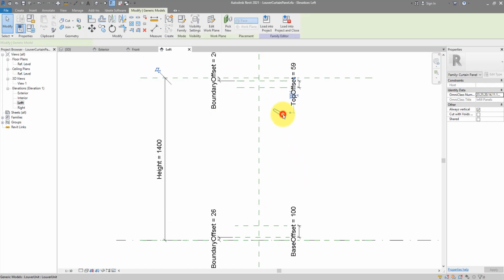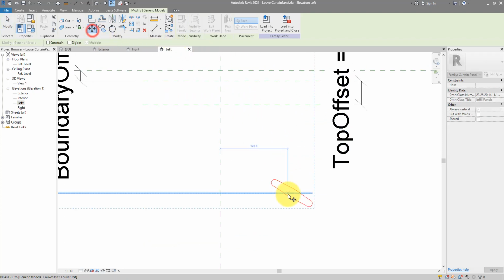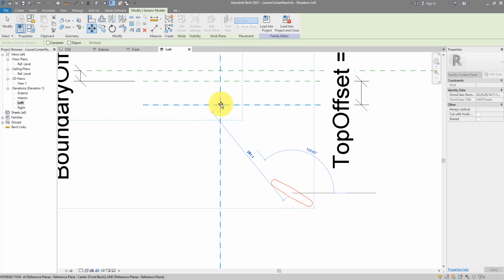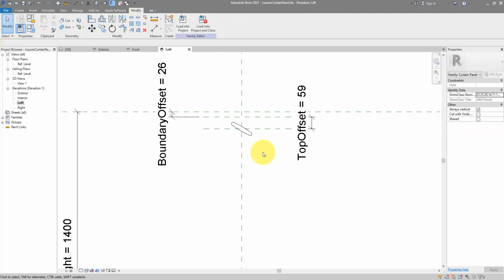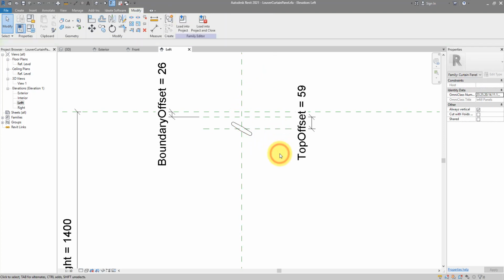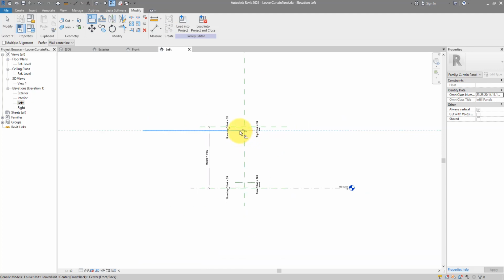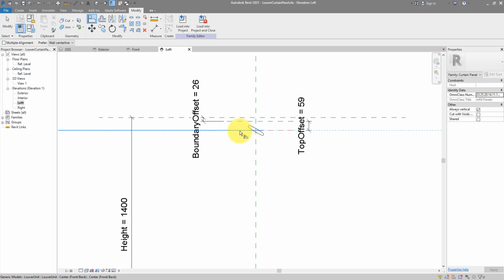Alright, looks like we're ready now to move our louver unit to where it should be. Let's go to the move tool and bring it right there. Now, to make sure it's going to stay there where this plane intersects with the other one here, we need to lock it into position. And here comes the double alignment trick once again. Let's go to Align, select this plane there, and lock it to this horizontal plane in the family. You can see there's a long one that's sliding up there. Just click it and choose to lock it.